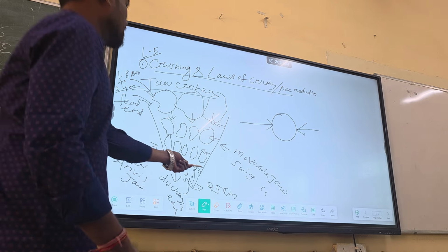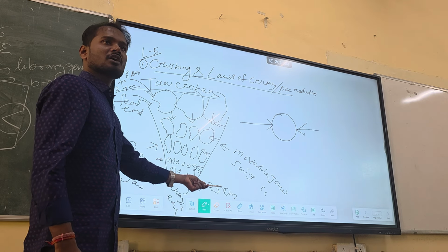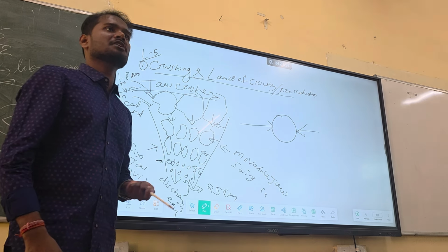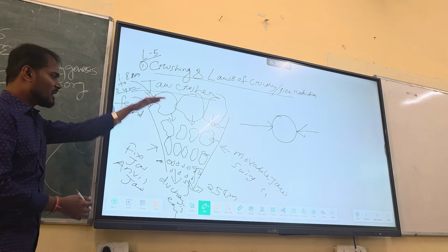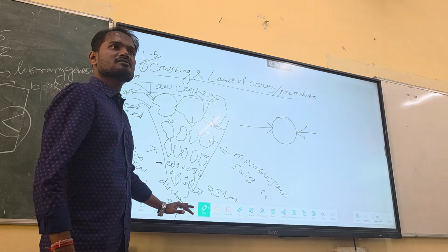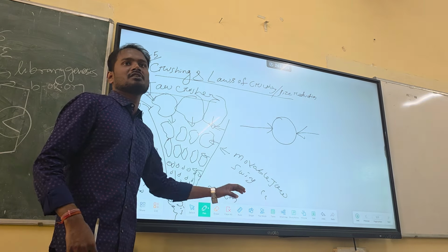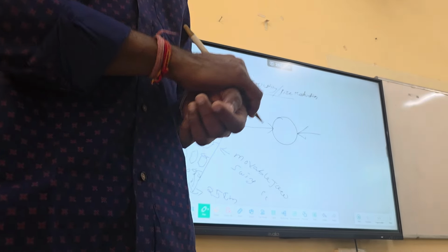You can convert this into meter and you can find out the reduction ratio. Reduction ratio is what? This size by this size. Okay? Fine. Feed size by product size. That is reduction ratio. Just you need to convert the unit. Either convert into centimeter for the top one, then you can do it. Otherwise, you convert into inch, or if you have inch here, you can have inch here also. You can do that also. Unit should be the same, no?